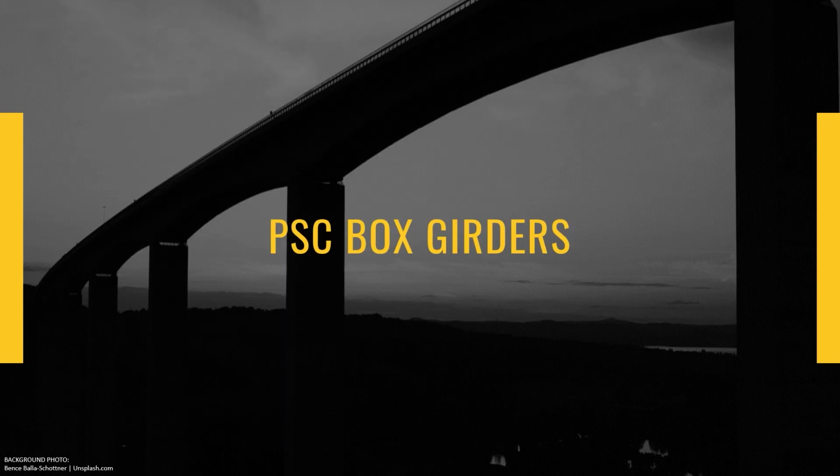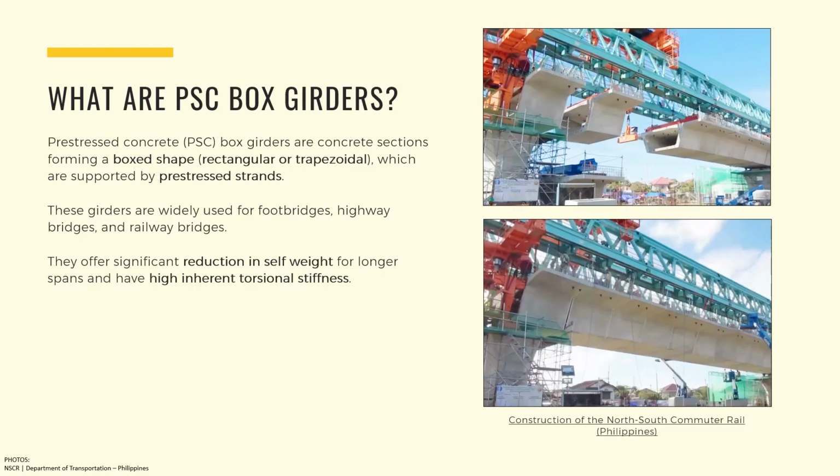So to start the presentation, let's discuss PSC box girders. Some of you may be asking, what are PSC box girders? Pre-stressed concrete or PSC box girders are concrete sections forming a box shape, which may be rectangular or trapezoidal, that are mainly supported by pre-stressed strands. This type of girder is widely used for footbridges, highway bridges, and railway bridges. PSC box girders offer significant reduction in self-weight for longer spans and have high torsional stiffness due to their closed shape.